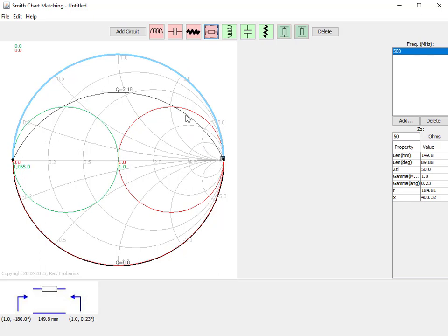And then also the math can tend to blow up on the edges here too, because of divide by 0 and things like that. So really the Q on the very edge of the chart might start not making 100% sense. But the key takeaway here is that if I get to a 90 degree length, then what we'll see is a 180 degree phase shift on the chart.